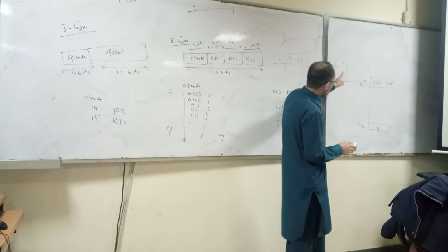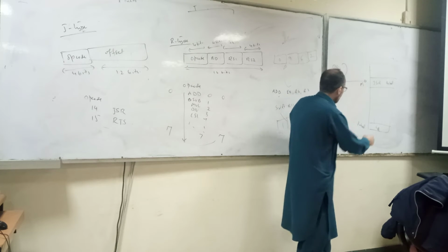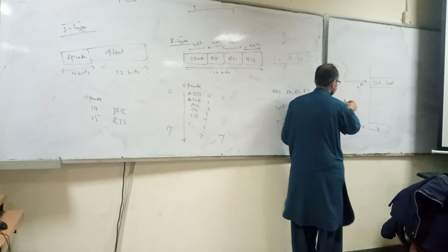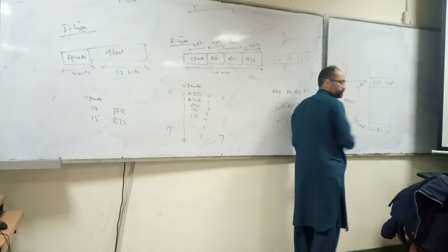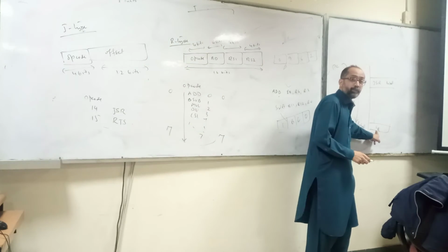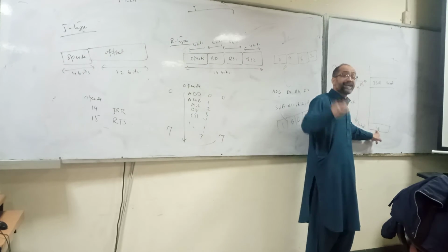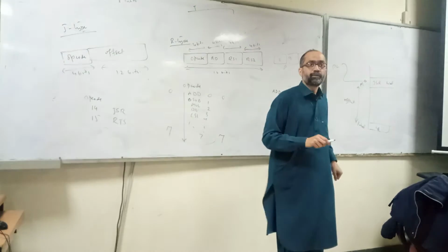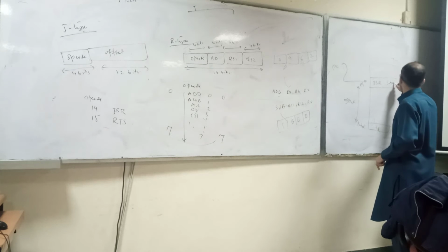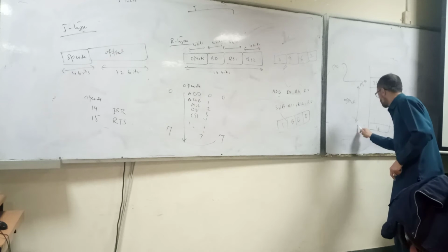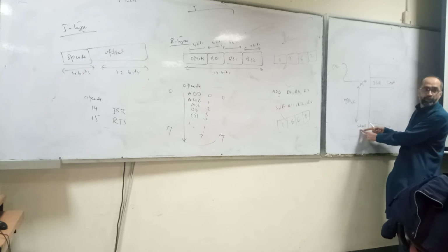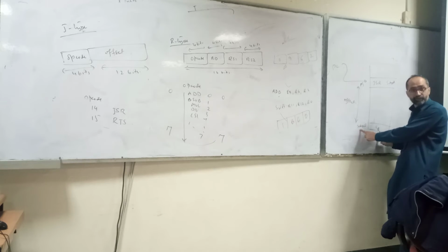Now the program counter is pointing to the address A. What is the difference between this label and address A? Offset. And you want to jump to IK, and IK is actually the address of the first instruction of the subroutine. If I say JSR subroutine, it will move here, to the address of the first instruction of the subroutine.